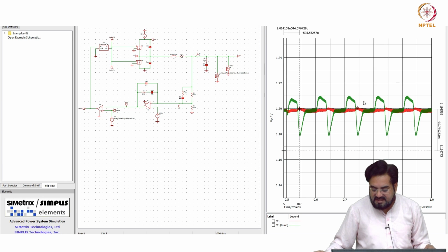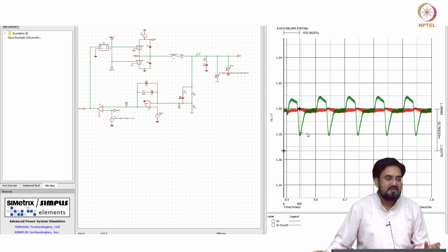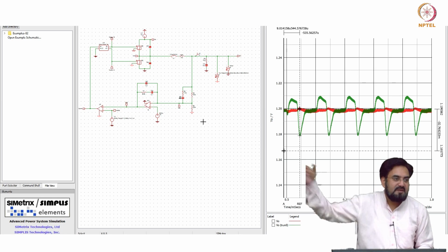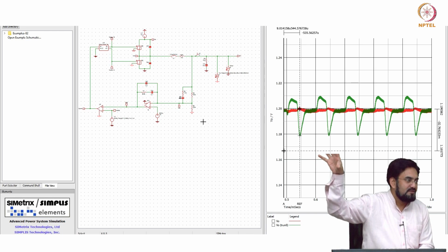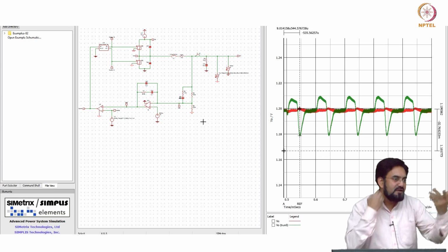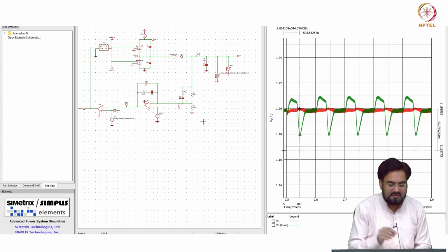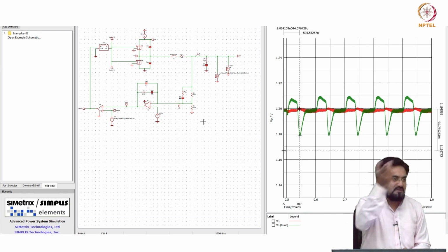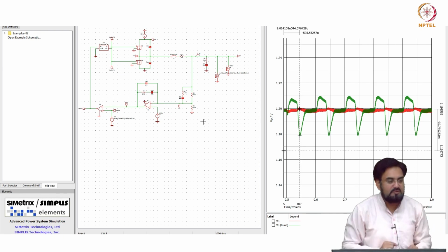And some of this will get suppressed by the loop gain because this is appearing at low frequency, and your bandwidth is 100 kilohertz. Think about PSRR: anything below your UGB, the loop will try to suppress. The same thing is here, you are having a ripple at the output at low frequency. So it will be fed back through your loop, and your loop gain will try to suppress that, and that is what is happening here.